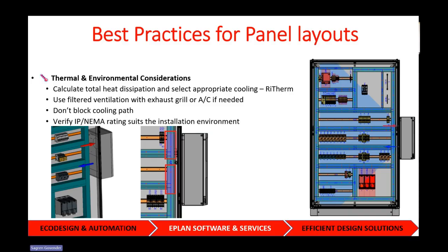I think we must have touched on this, but just make sure that you've got the correct enclosure for your environment. If it's in a high dust environment or in a wet area, outdoors, or whatever, just make sure you've got the correct IP rating or NEMA rating for your panel.